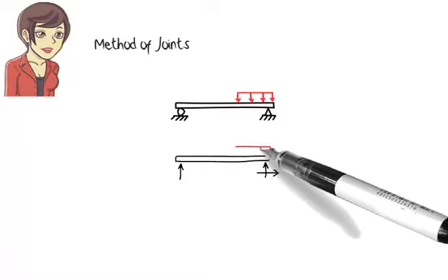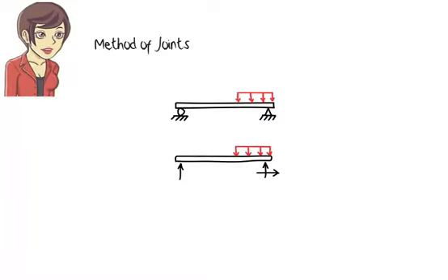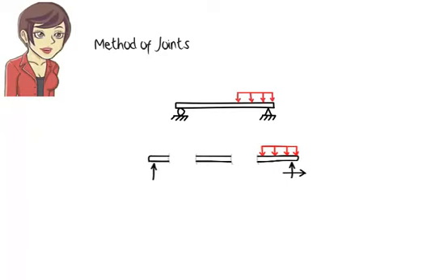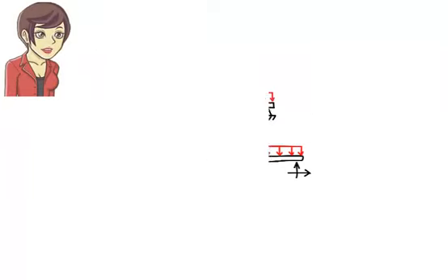For example, if conceptually we cut a beam into 3 segments with the correct internal forces shown at the cut points, then the equilibrium equations must be satisfied for each segment if the entire structure is to remain in equilibrium. We can apply this principle in order to analyze statically determinate trusses.